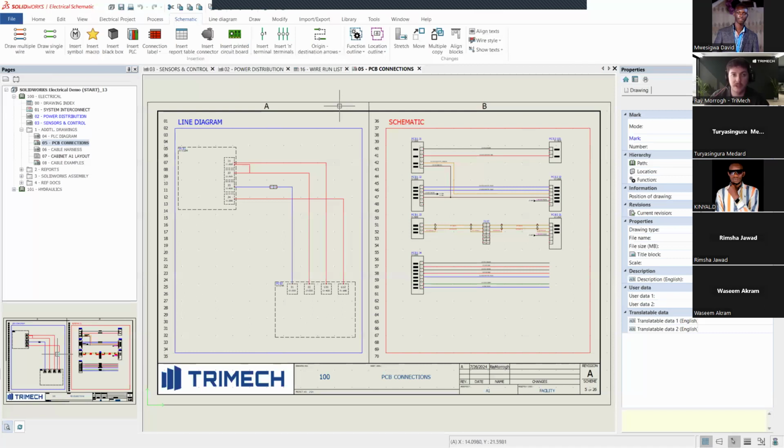And if you want to bring your PCBs into a 3D environment, that's something SOLIDWORKS itself is already capable of doing using CircuitWorks, using the proper file formats. Where SOLIDWORKS Electrical can come in handy is if you are interfacing those PCBs with other components that would be relevant to have in an electrical 2D schematic diagram.